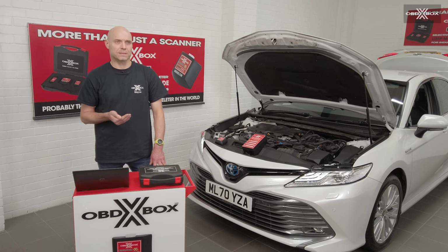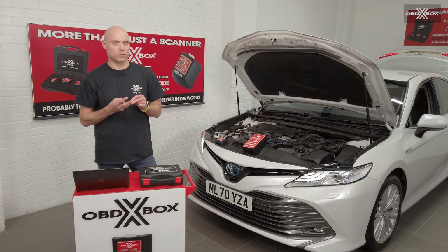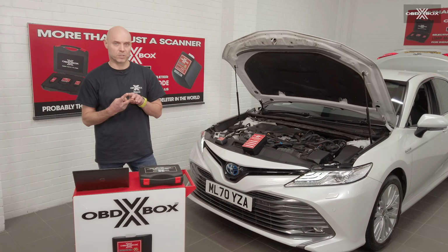Usually that is adequate to pinpoint the fault, but sometimes if it's comparing 3 variables and 2 of them are at fault, it'll sometimes put the item that is not at fault as being the fault code because there's parity between the 2 faulty parameters. So you're getting an incorrect code.